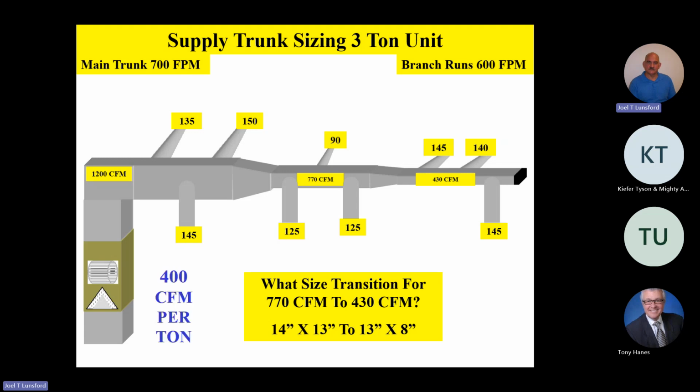And so taking a look at those last 3 takeoffs, what size duct would I need on those last 3 takeoffs for 145, 145, and 140? What size duct would I need with a damper? 8. Okay, good, excellent.